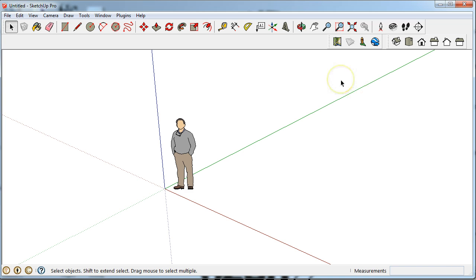The first thing that I would like to do is go to the Google tool, which says Add Location, this little shortcut right here. This location tool is going to allow us to take geographical information from Google Earth, the GIS, Geographical Information System, which is basically going to allow us to get the coordinates and bring in the topography of the actual land site that we are going to be surveying. The land site we are surveying is Irving Middle School and the property that it sits on.